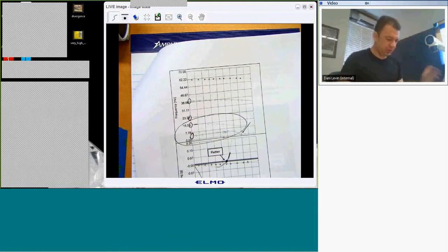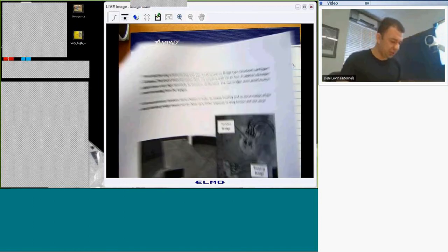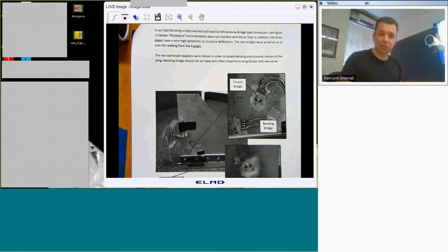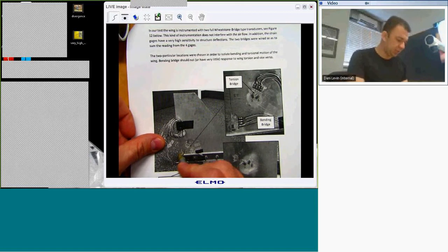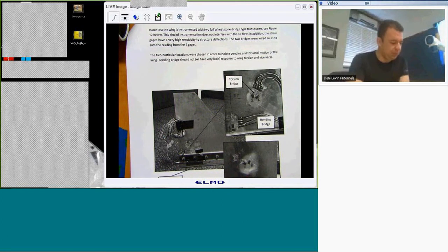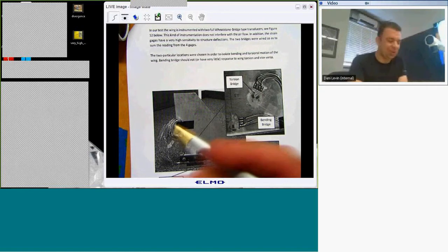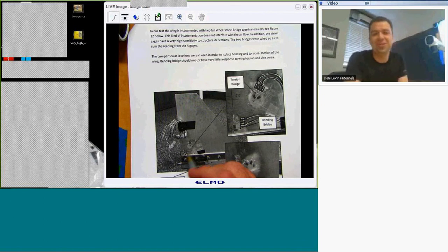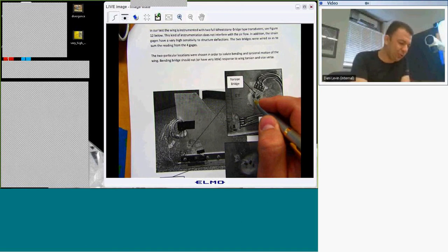Okay, so for the purpose of seeing each mode separately, I did instrument this wing, and I hope it will work as it should. So we have two bridges here. This one is the bending bridge. It's located at the highest bending strain location. How do we know that? Well, if you bend this plate, you will have some kind of hot spots. And this is our torsion bridge.